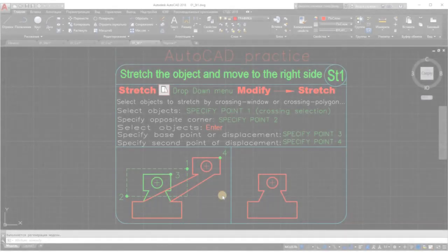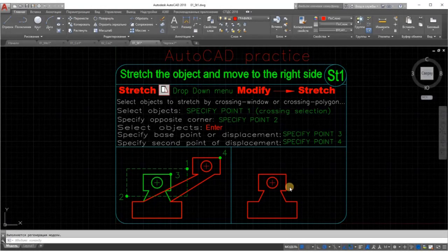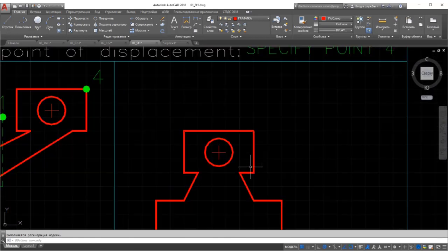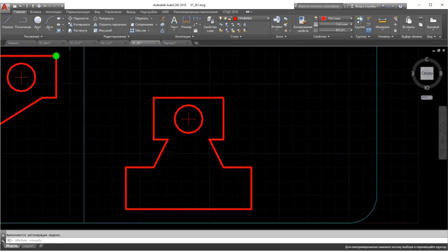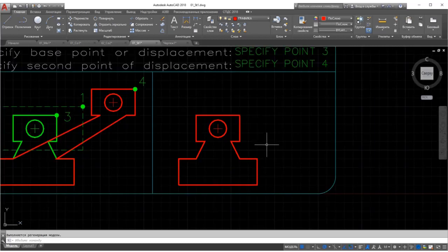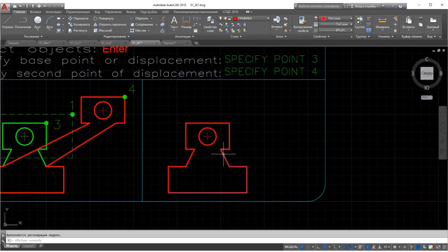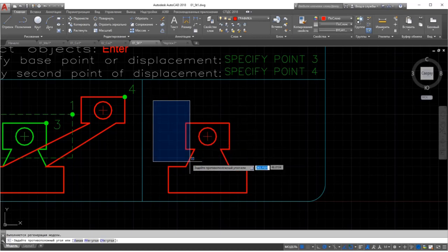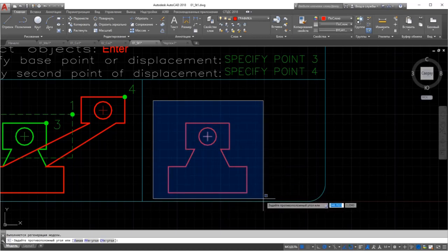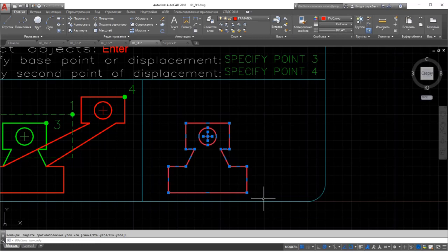Crossing object selection. If you click a blank area of the drawing that is not an object, you're implying to AutoCAD that you want to specify a selection by dragging a window through the objects. If you move the crosshairs to the left before picking the next corner of the selection area, you're implying that you want to select all objects that reside completely within or touch or cross the selection area boundary.